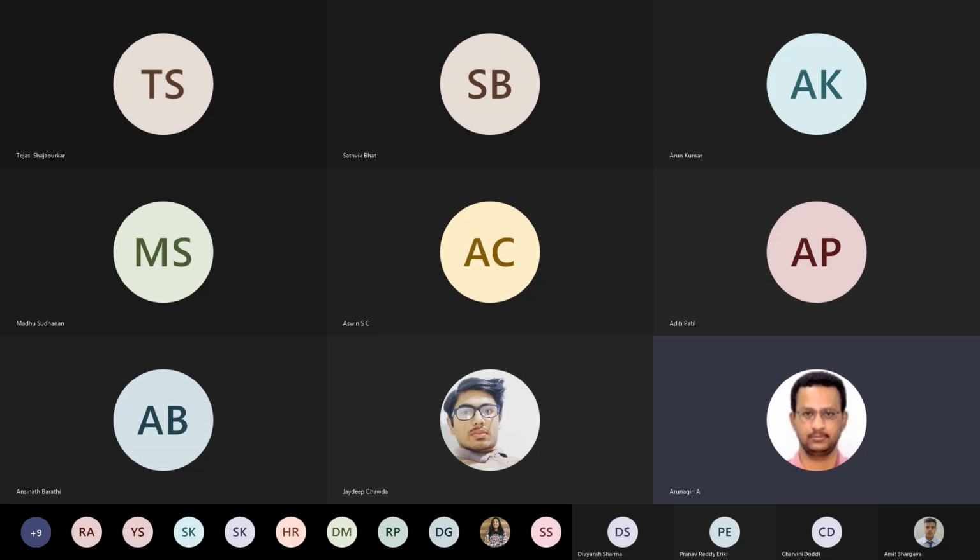There are different streams: A stream, then B stream, then C stream, that is bundle to shell, then E stream, that is baffle to shell, and F stream due to pass partition plates.